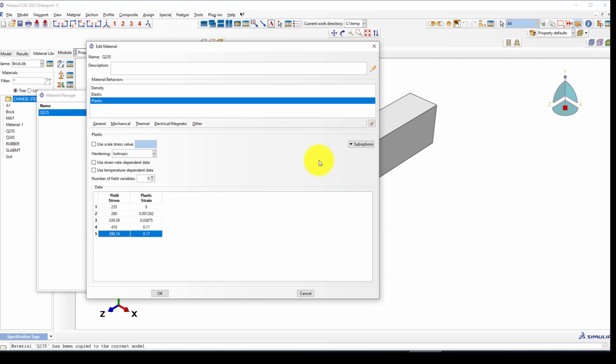The steel curve first starts in the elastic region, then goes to the plastic, then a little degradation, and then it quickly drops down. So we can consider that degradation as well. In some tutorials, we consider only until this area, but it's approximately true to consider this as well. So I will take this one. In case you have any doubt about the result, you can delete and check this area, add these parts again and compare the result to see how it behaves.